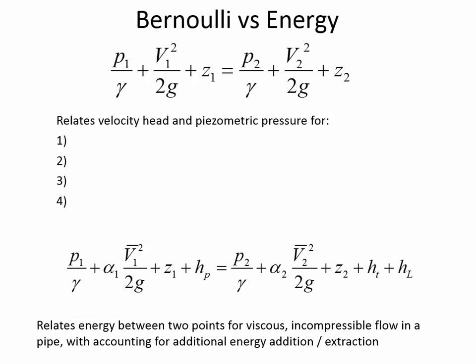Like if you've got water flowing through a pipeline, most of the energy is going to be lost due to pipe friction. And the amount of energy that's lost because of a couple of bends and a few valves, that's a much smaller fraction of how much energy loss there is. But there are some situations where actually the local losses exceed the frictional losses. So, any questions so far about the energy equation?